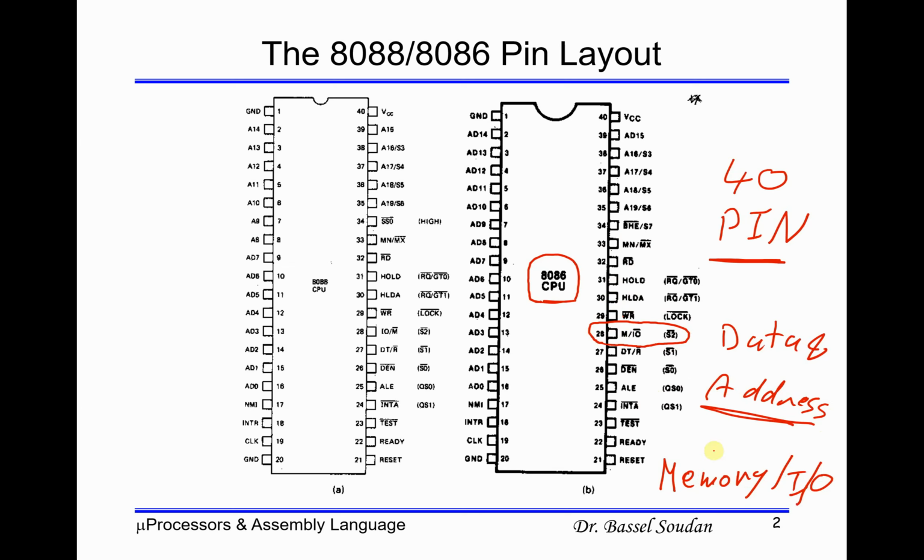So basically, there is no specific pins dedicated for the microprocessor to talk to the memory and dedicated pins to talk to the input output. Those pins are shared between the memory and the I/O. So this brings the direct question we can ask: how can the output devices or the processor himself know whether he is now interfacing or talking to memory or I/O?